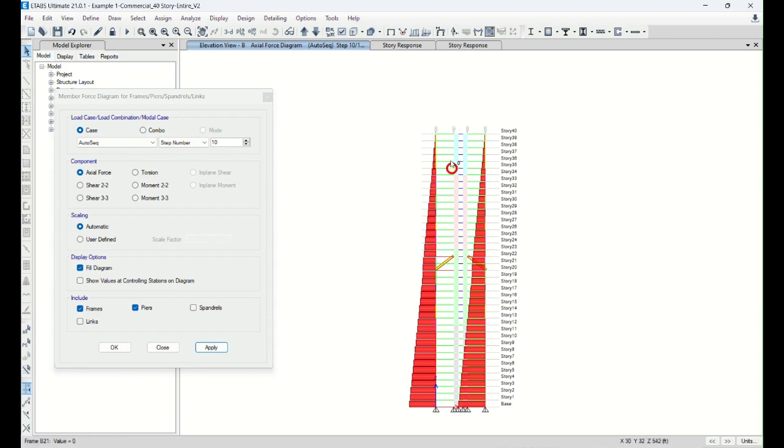But after our construction is completed, we tie the bracing element, which means bolting, right? So that at that stage, this bracing is activated and holding some actual force. So since in this sequence analysis we just exclude it during the construction and tie this outrigger at the last minute, you see the compression forces are kind of gradual again.